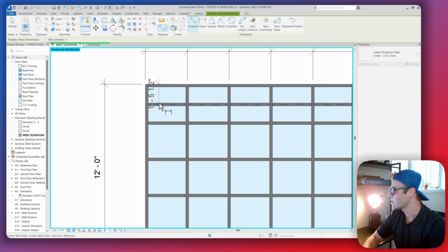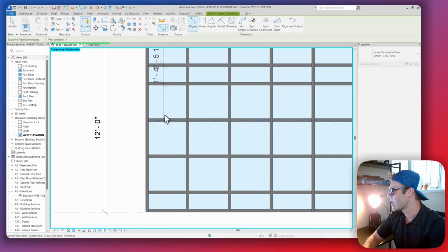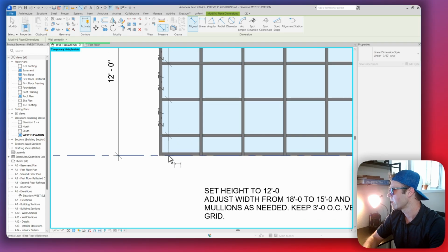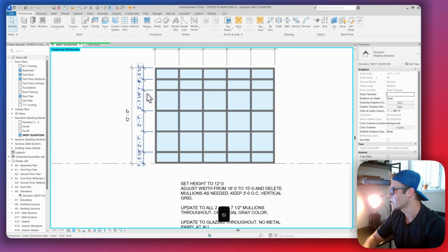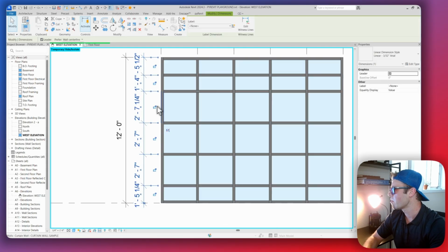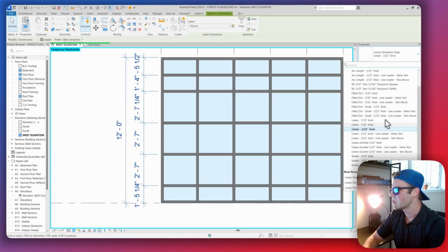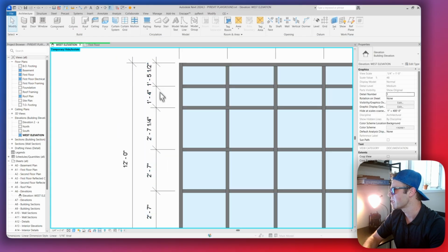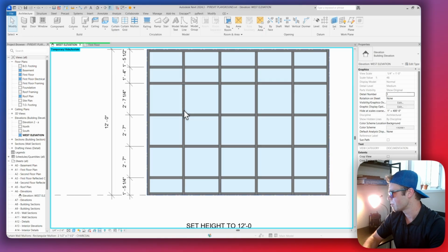So we're just going to click on the top. Again, same thing with the verticals. You can't select the middle. So we're just going to select the top of that top grid. And then we're just going to go down selecting the midpoint or the grid line of all of these and getting to the bottom, right? And then bring that over. We can make this smaller if we'd like. See how they're overlapping? Can't see them very well. So let's make both these smaller. Let's make them 1/16 inch text so that we don't have to shift them to see them. I like to do that sometimes.